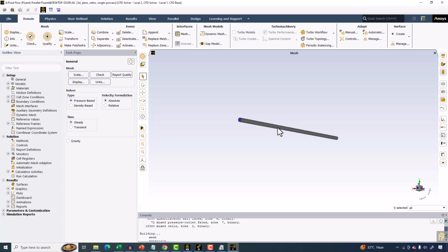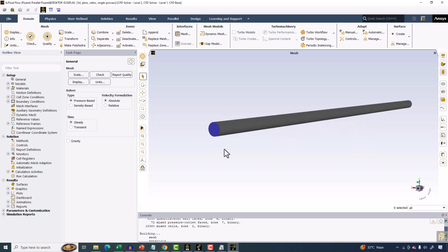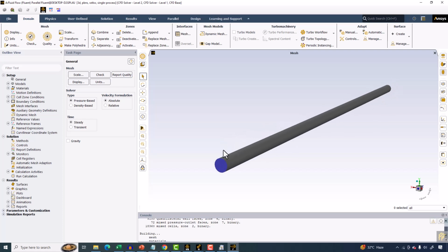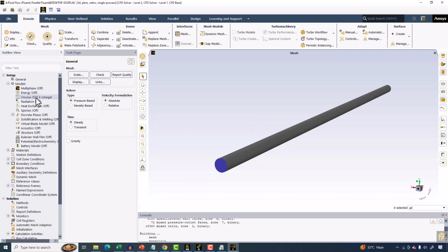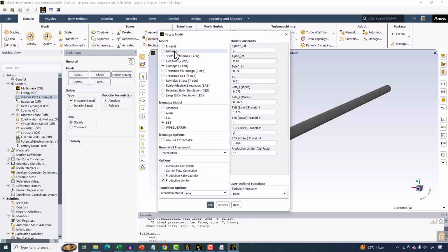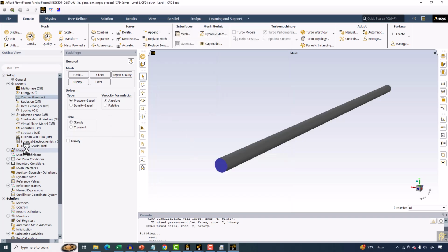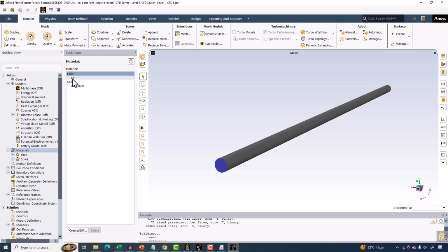In Fluent, one thing we will be prescribing is our boundary conditions. The geometry is already here, so there is no need to define the length or the diameter, and the fluid properties. Before that, we will go to the general settings: pressure based, steady state, it's a steady state case. I will go to models, and from the viscous, I'm going to select laminar flow.